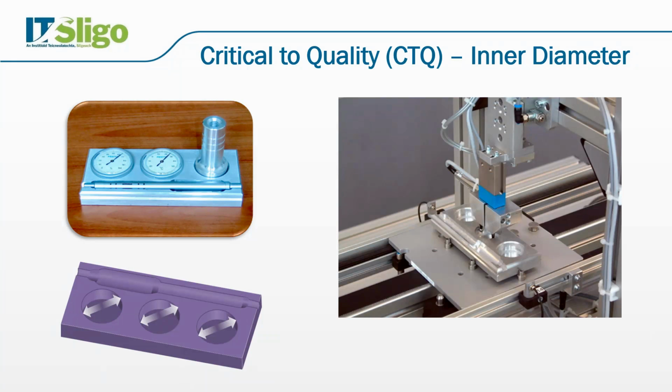Let's choose the example of the pen holder and apply control charts to this pen holder. The critical to quality characteristic was the inner diameter. We're going to take measurements on our process as we are producing these parts and use these to control the production of our pen holders. Let's choose one of these inner diameters.